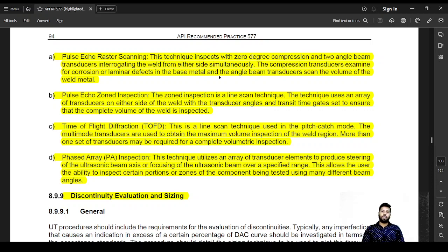These are some of the most established techniques, which are considered to be advanced UT techniques. Manual UT will only tell you about the discontinuity, and other things are guesswork or subject to calculations. But TOFD is going to be one of the best techniques to identify cracks or the length of the cracks, and it generally gives you a B scan image. Phased array is generally going to give you a scan image and it will scan the entire section of the weldment.